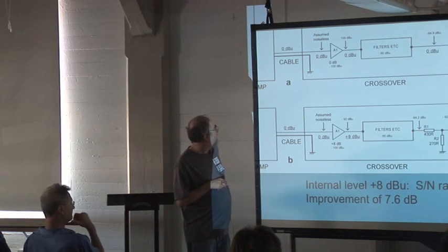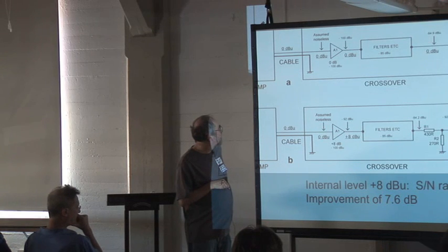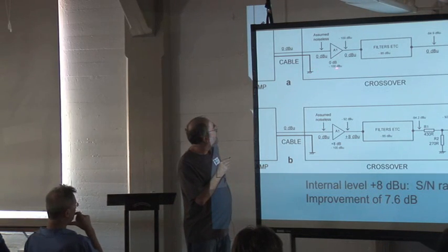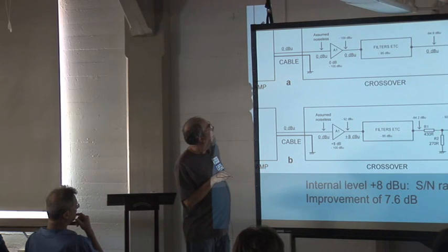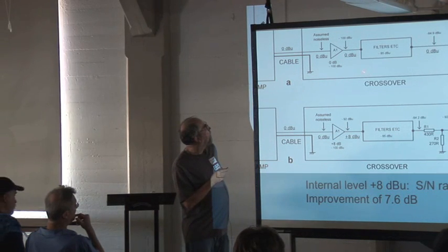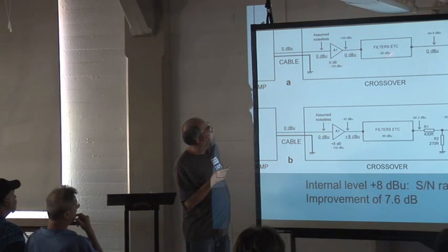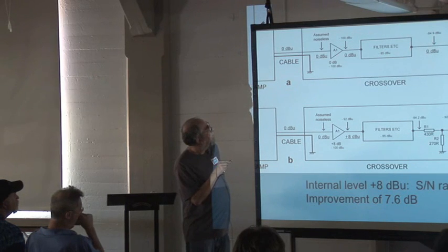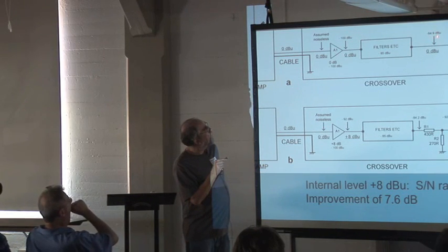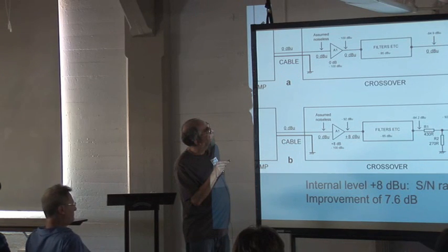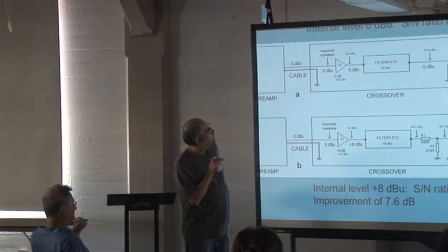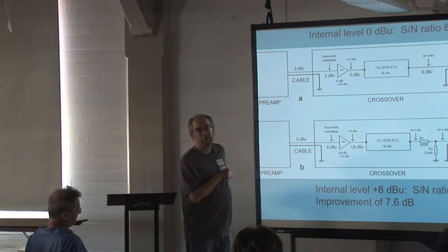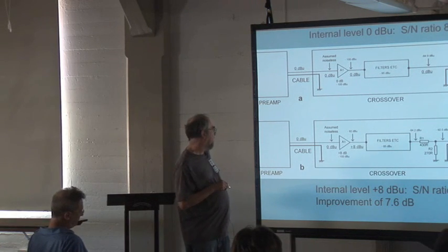Okay, right. So we're assuming in this signal path that the internal level is 0 dBu, which is a fairly common level. A lot of systems use -2. If you make certain assumptions about the noise, like your input amplifier is -100 dBu and all the filters are -85, you're just looking at one path here, of course. Then you add this up and you get -84.9 at the output, going into your power amplifier, which is not very low, really. That's not my idea of low noise.